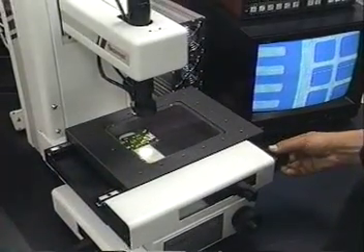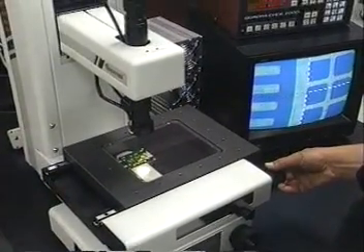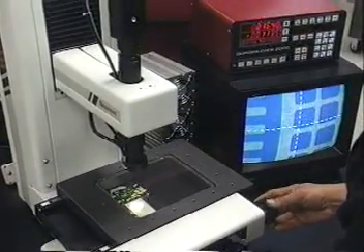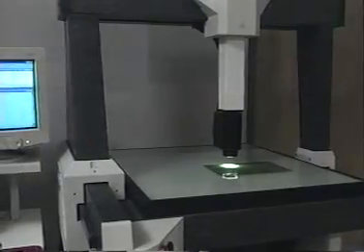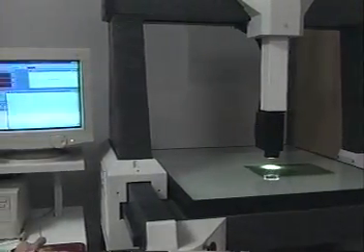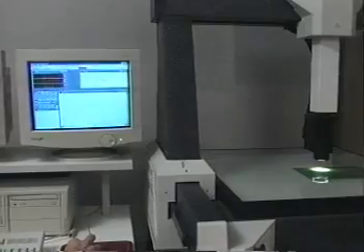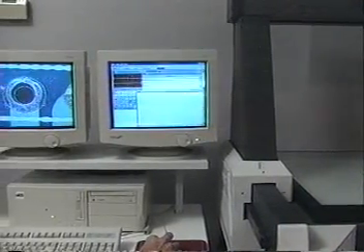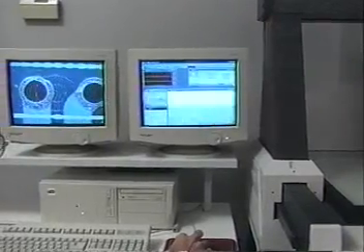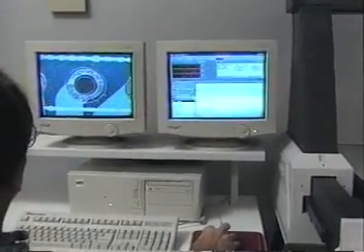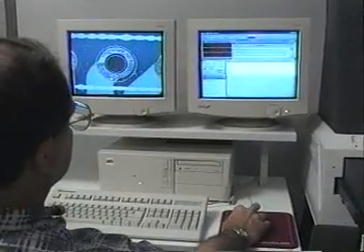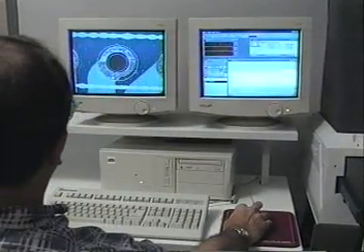In a typical vision system, a part's image is captured, usually with a video camera, to measure its relevant features. This information is converted into electrical signals, which are then analyzed by a computer. The collected image is compared to predefined criteria, including desired dimensions and allowed tolerances. The image may also be analyzed for defects, such as cracks or scratches.